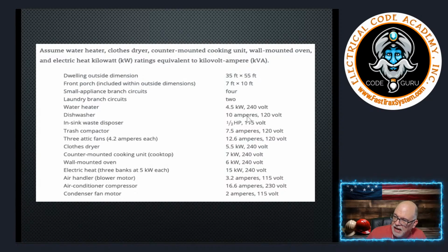We have a 10 amp dishwasher, which we're going to have to convert to VA. And y'all know how to do that, right? The amps times the volts is going to give us a VA value that we're working with. You should always know that to convert, you have to work in the VA. So that's how we convert VA.